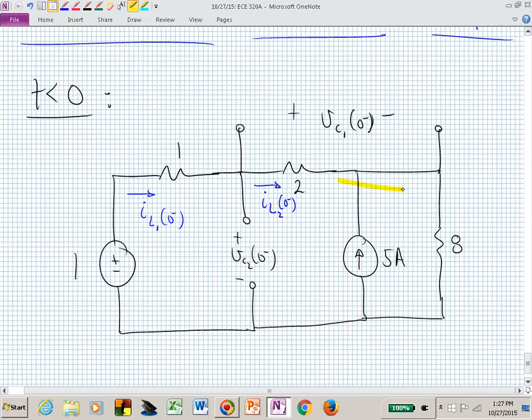Do you see that if I look at the currents leaving or entering that node, I would have the ability to determine, let's say, this voltage, V sub x? And if I have V sub x, then I can start solving for all of these currents, and once I know the currents, I can also start finding these voltage drops. Let me say that this is node A.